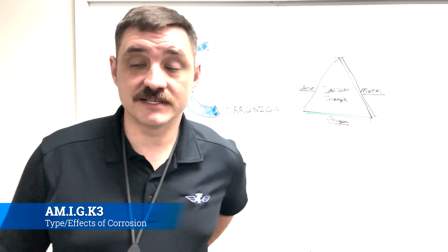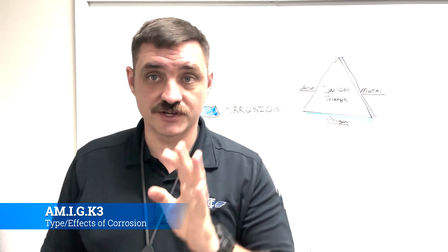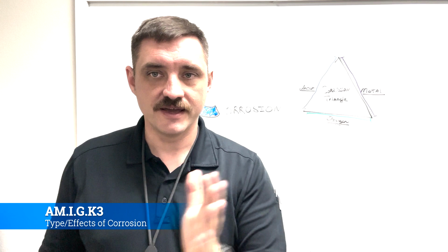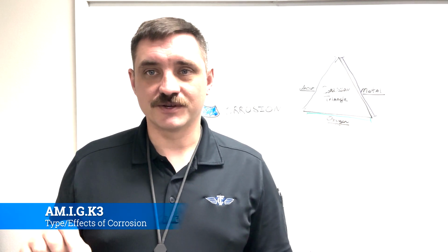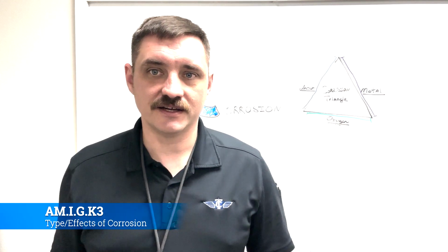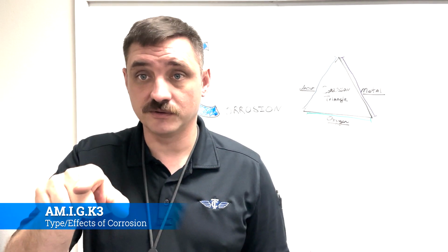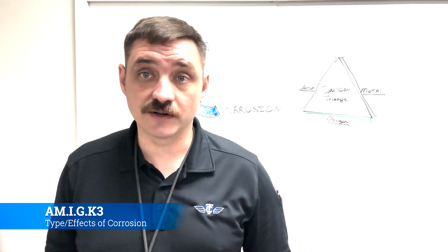And what will end up happening is that you'll have a point of origin, and the corrosion doesn't just go straight out, and it doesn't go into a nice uniform wave. It just kind of meanders, and it's doing that all up and down that scratch. And so what it ends up looking like is almost spider-webby kind of corrosion. But you'll see where the original damage was, and where the filiform comes off of it. So that's filiform corrosion.